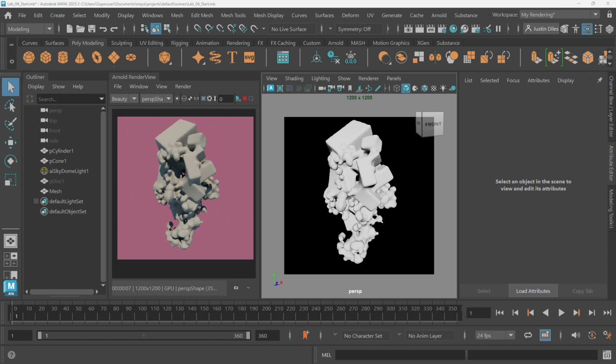Displacement is a great way to add a finer level of texture to digital models, and it involves using grayscale imagery, either developed in Maya nodes or with image maps or in programs like Substance Painter, and using that imagery to drive small polygons up and down. Those polygons may exist in the digital mesh, or they may be added at render time, and we're going to cover how to set all of that up.